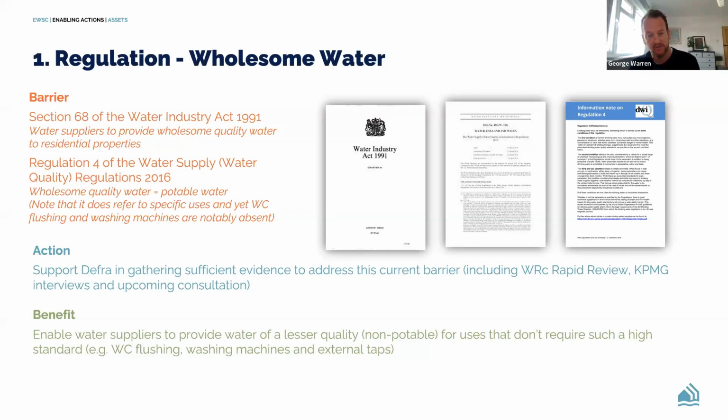And understandably, the majority of people say, well, what on earth is wholesome water? Then you're pointed towards Regulation 4 of the Water Supply (Water Quality) Regulations 2016. I know it's sounding riveting, but effectively that states wholesome water equals potable water. So you read that as water supply companies can only provide potable water to residential properties, which makes it very difficult, therefore, to provide anything other than your standard drinking water.